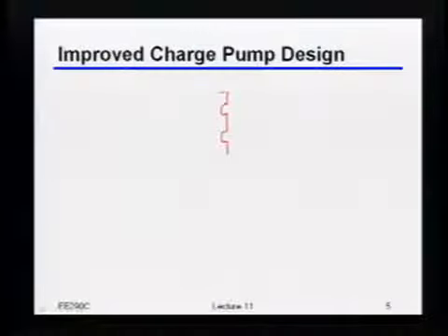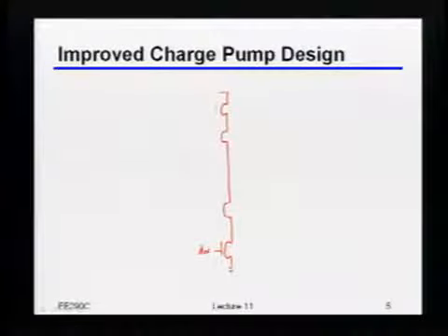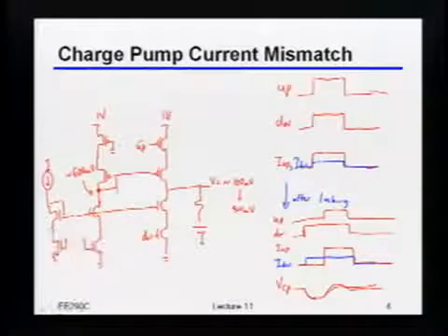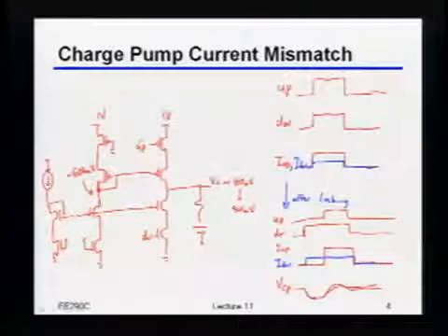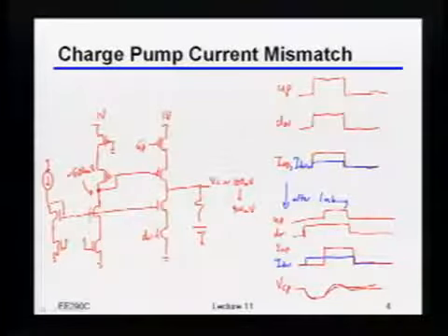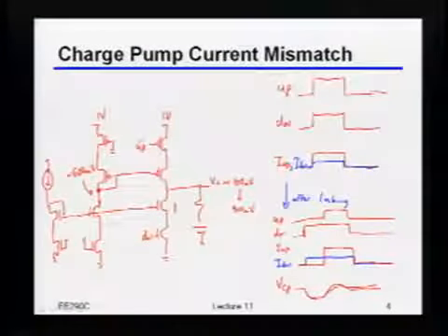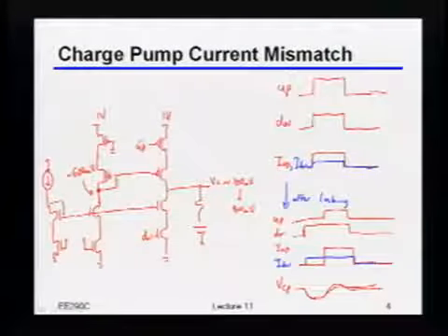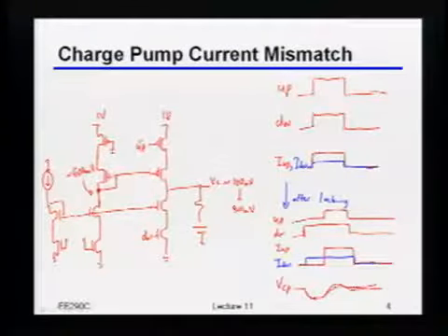So again, this is going to be my main charge pump, and I'm going to leave myself some space because I'm going to be throwing in an op amp here in a second. But you can tolerate some mismatch between that reference branch and the final branch, right? But it's really a matter of the top and bottom matching. If there's mismatch here, that will become up and down mismatch, right? Because the mismatch here has nothing to do with the mismatch here. If I just happen to throw in a random threshold voltage mismatch between these two pairs, it has nothing to do with this over here.